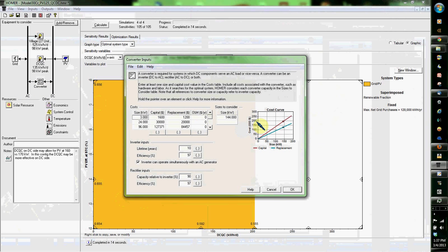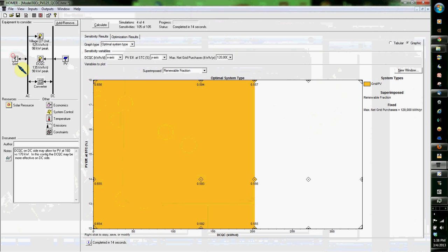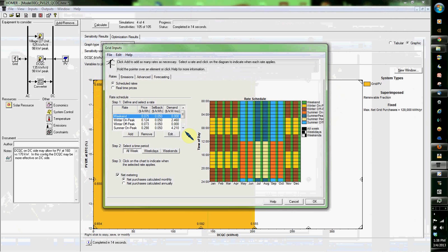Now, the inverter. I was doing a study, so for my purpose I was using 6 inverters in parallel for an entirely different reason. But the way HOMER works is that you can have as many as you want here. I was modeling after the inverter, and theirs was 24 kilowatts for about 30,000. And so I've got 6 of these, and of course my price is significantly higher, but for what I was doing, this is what works, and you're allowed to set the efficiencies as well as the rectifier and lifetime. I now am using the grid as part of a power source as well.